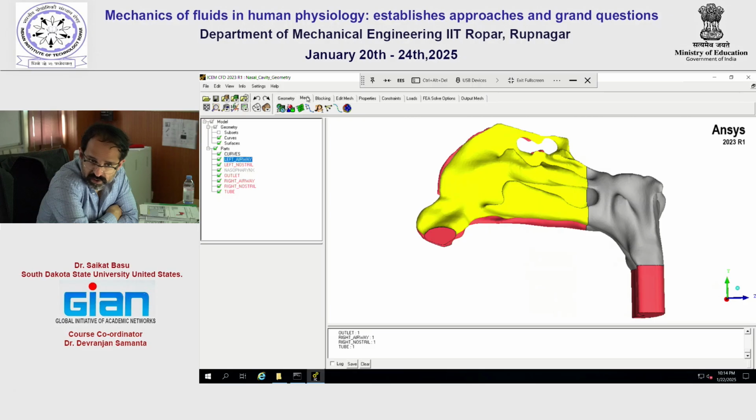And once the tetrahedral mesh has been built, you can use it for simulations, but there is this caveat that eventually for the biomedical applications in this space, you are trying to get regional deposition patterns, be it for infection transmission or for drug delivery. So the mesh has to be resolved, ideally, near the regions where you are tracking that particle deposit.